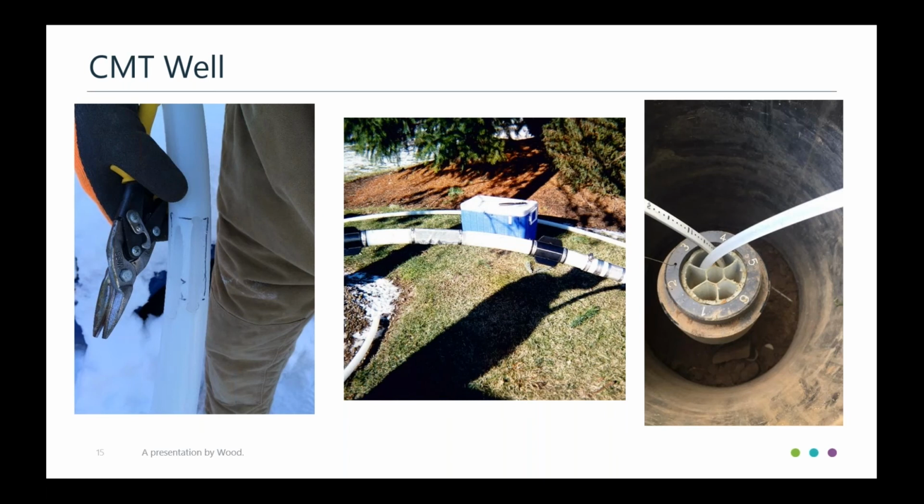What you end up doing is cutting holes for the screen on the channel. We opened up 2 of them so that, as you can see in that last slide, you can have water level in one, tubing in the other, and you can do your low flow sampling quite easily. You cut the holes, you wrap the screen, you decide on your screen length, you're plugging up the ends to make sure you're not getting anything, and you build your well. And you can do multiple channels. The way we have it set up, we'd end up with 3 and just water level in the middle.